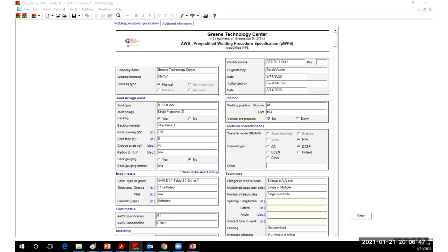Yeah, this got brought up on a job site. We had a welder certification that was generated using the forms, and the form still had the WPS from the sample on there. I'm not sure that you actually qualified him with the WPS. This was actually one of the schools that did this, and I was trying to get a hold of the welding instructor at that school to tell him what he needed to do. And one of the things that I do is I give a copy of the WPS that's used for testing to the welder if he wants it.